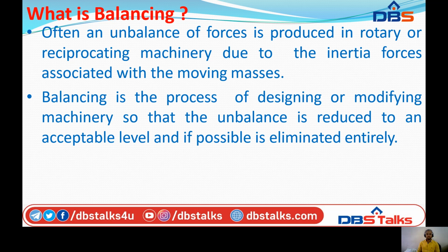The high speed of engines and other machines is a common phenomenon nowadays. It is therefore very essential that all rotating and reciprocating parts should be completely balanced as far as possible. If these parts are not properly balanced, dynamic forces are set up. These forces may not only increase the loads on the bearings and stresses in the various members, but also produce unpleasant and even dangerous vibrations.